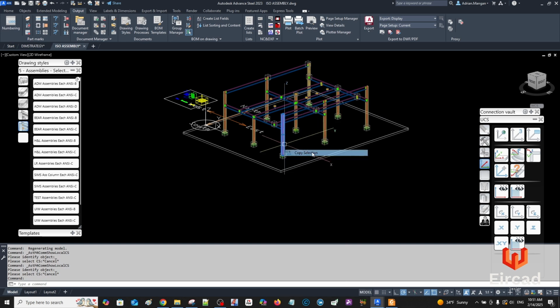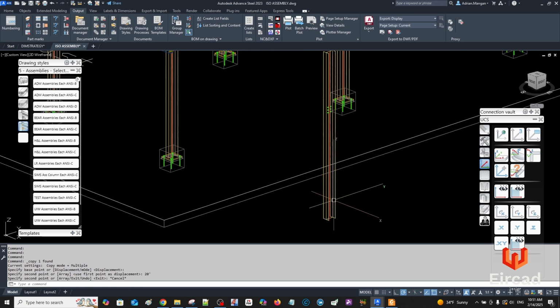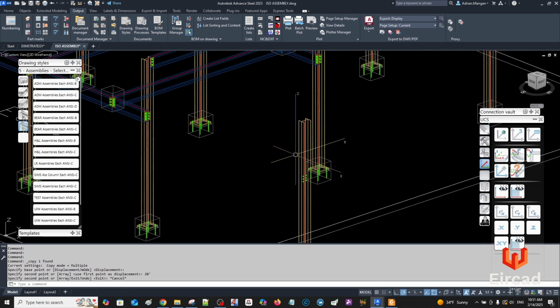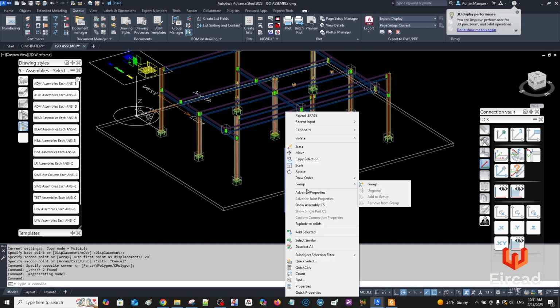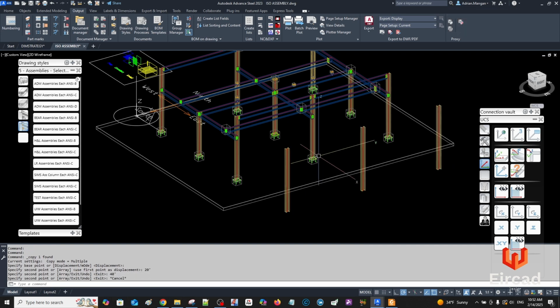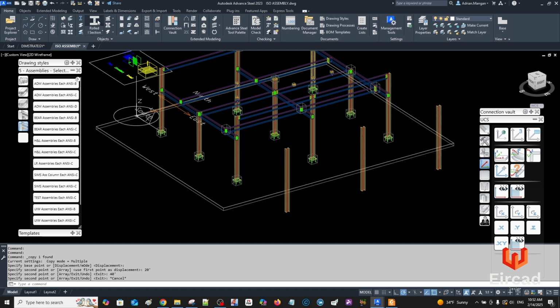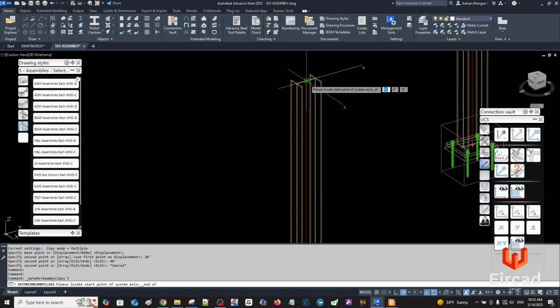So if I copy this over here, 20 feet. This column has some holes in it, which we don't really need because we just copied it. It also has a feature on the bottom, but we won't worry about that for now. So I'm going to copy this 20 feet, 20 feet, so 20 and 40. If I want to draw a beam here, what I do is I go to the node point, so I'm not risking snapping to something else.